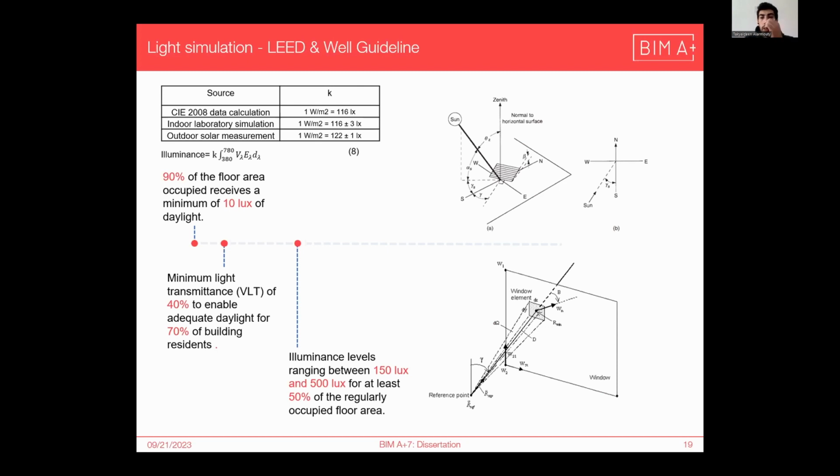These values are known by involving equations with the model and performing calculations. The daylight in the building is calculated and the values are verified. We noted in the figure at the bottom of the screen on the right, the vectors, or lines, connected between the point on the workplane and each corner and the middle of the windows to calculate the daylight factor.